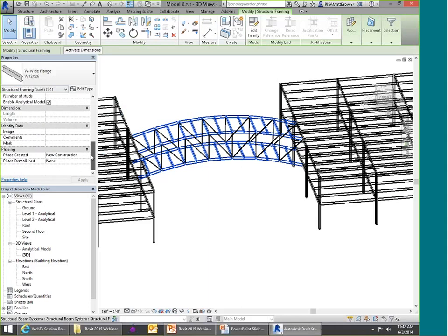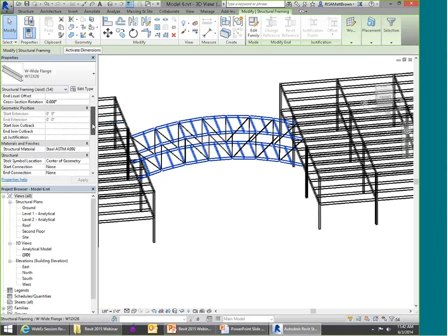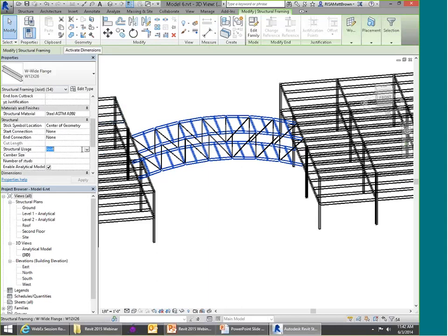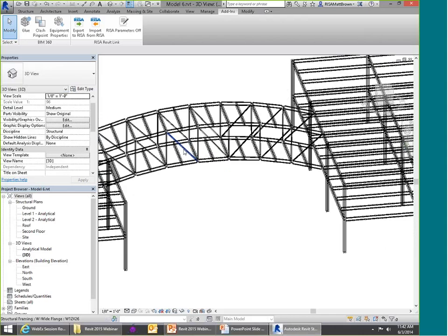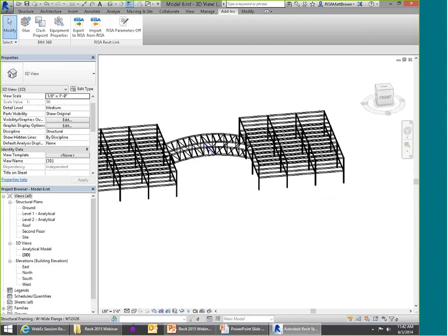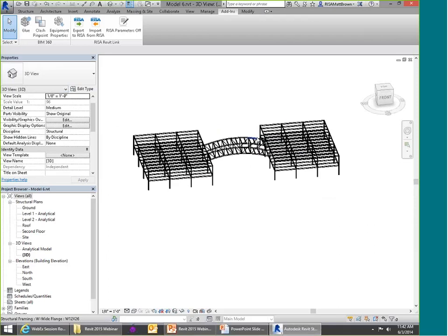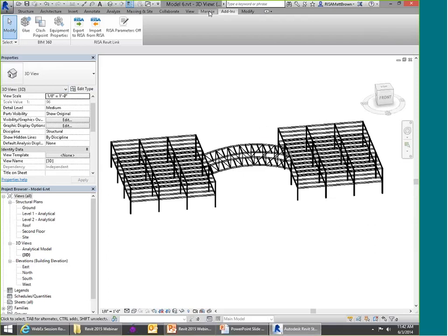And you'll see that there's a special code in here in Revit to define the structural usage. And whether you call something a girder, a joist, an other, or a purlin, it's all the same as far as RISA is concerned for analysis. But horizontal bracing is a little bit different. If I say that all of these members are horizontal bracing, we still get the same code checks for bending and axial and everything else as we would get for beams, but that's a code that tells RISA Floor to ignore that member.